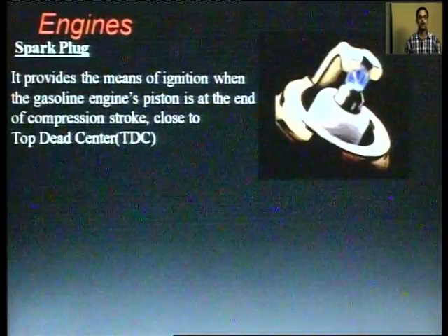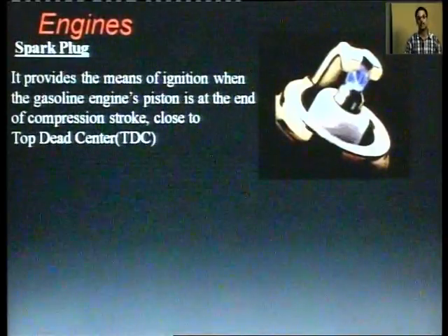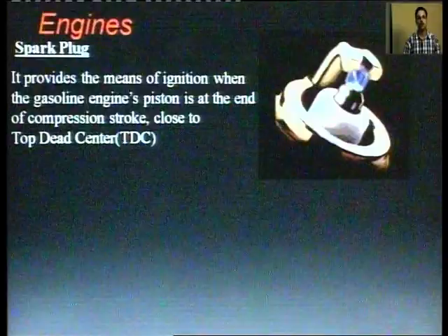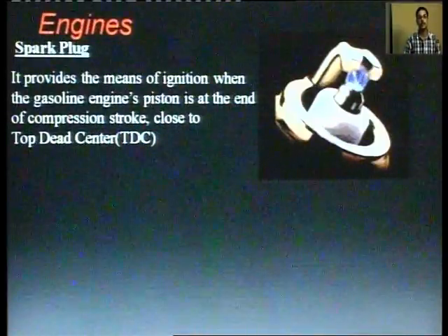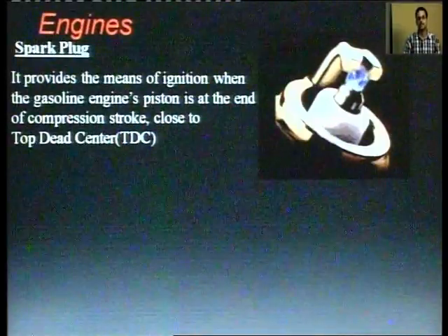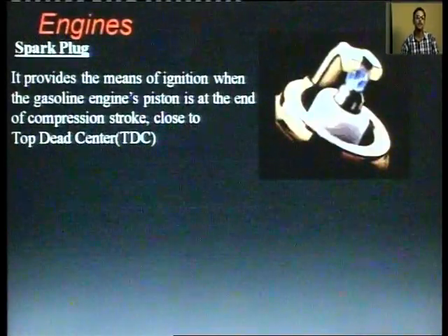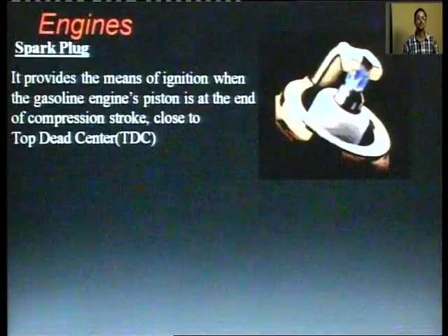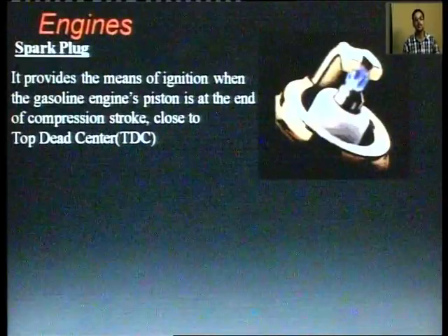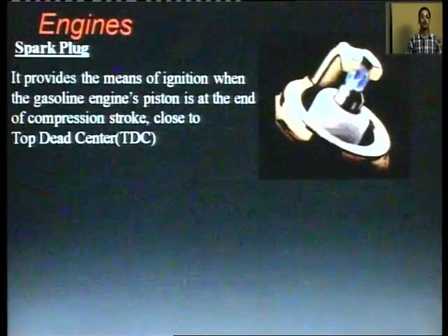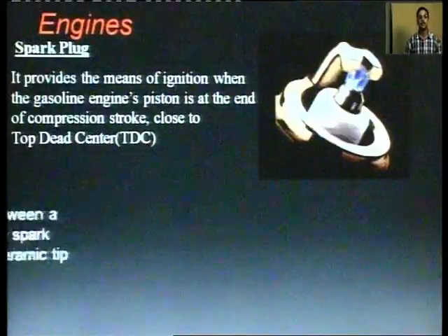Spark plug. This is the component which ignites the fuel. It provides the means of ignition when the gasoline or fuel mixture with air enters the engine's cylinder. The engine piston is at the end of the compression stroke, close to the top dead center. Generally the spark plugs fire close to the top dead center.